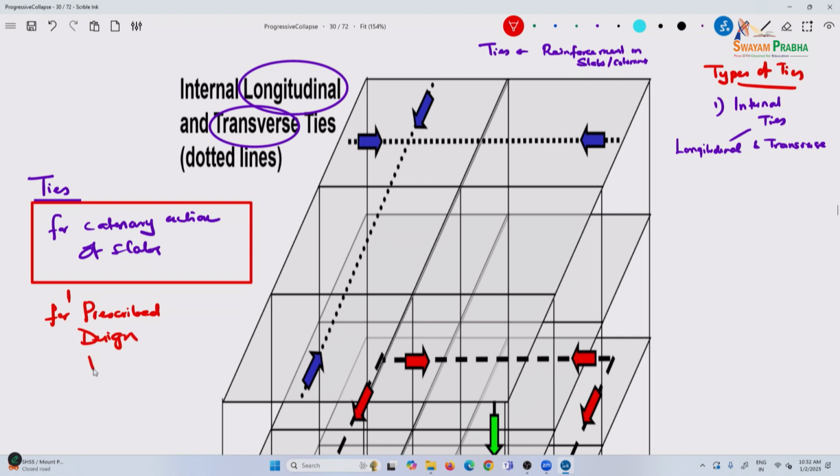So, there are two types of forces in design: calculated, where you go through an analysis and get a force. Otherwise, for example, lateral bracings, there is no calculated force. You have a prescribed design force as so much percentage of the load. So, when you say prescribed, it may be a percentage of the applied loading.